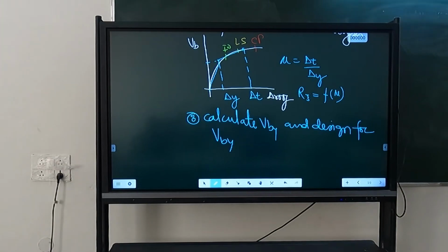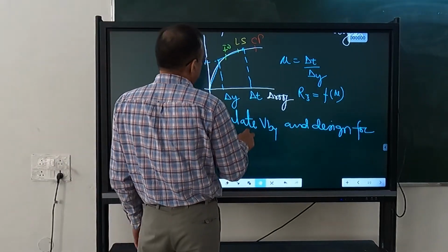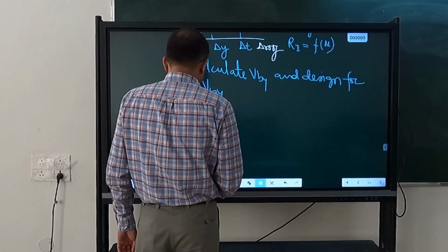We will convert this multi-degree freedom system into a single degree freedom system. Considering it in the fundamental mode, it is depicted as one cantilever. For a cantilever, the period can be calculated using EI. But I do not know EI. I am here to design my building. But EI will be obtained from that capacity curve of the preliminary design. Okay. We have to go for iterations. You have to calculate which period you should design for.